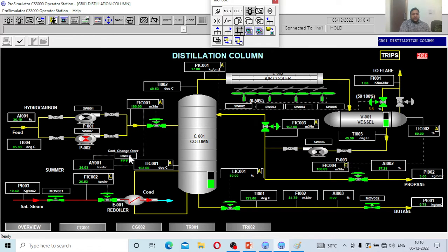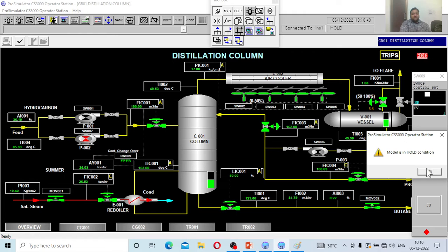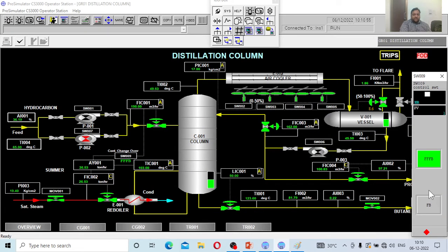That means if I click here, presently it is connected to the feed forward and feed backward systems. I can change to only feed backward. I don't want any feed forward. Okay, let me start this particular valve and understand how I'm going to change. The moment I touch it, it will receive the signal only from this particular sensor which is measuring the temperature. That means feedback systems. Now it won't take any signal from this particular line, which is the feed forward system.